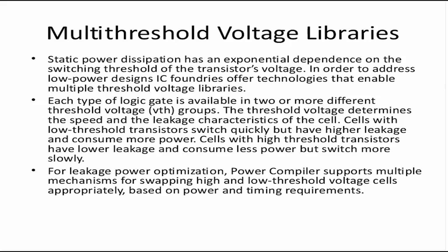Because even if the cells are slower, since we are working on low frequency or a large timing path, the high VT should be able to meet the timing, but it will consume the least leakage power. It makes sense. Again, for timing critical paths, you can incrementally try and replace high VT by standard VT. If the timing does not meet, you will probably go to low VT.